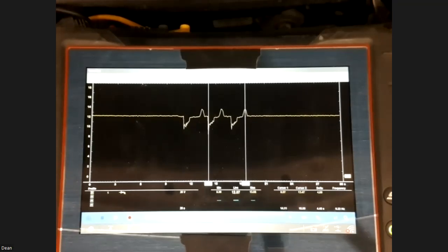This is a vehicle that I'm in the middle of my computer analysis on. It's having electrical issues. I've already charged up the battery. So anybody out there saying, did you charge it up? Yes, we did. We gave it a full charge. It was up to 12.66 and the battery is still weak. So now we're going to have to replace it.